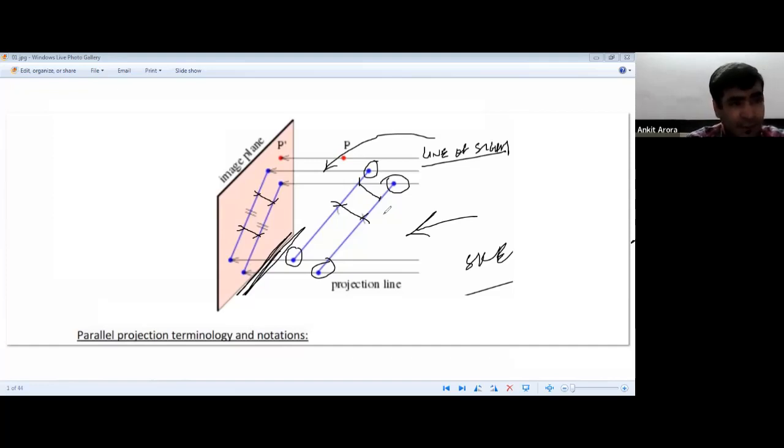But again, in oblique projection or parallel projections, you get the exact view of the particular object, how that object is. So this is the basic difference. When we talk about parallel projections, they are very popular in technical applications, obviously. Why is that? Because direct measurements can be taken from the image. And obviously your orthographic projections are more realistic as compared to the other methods.